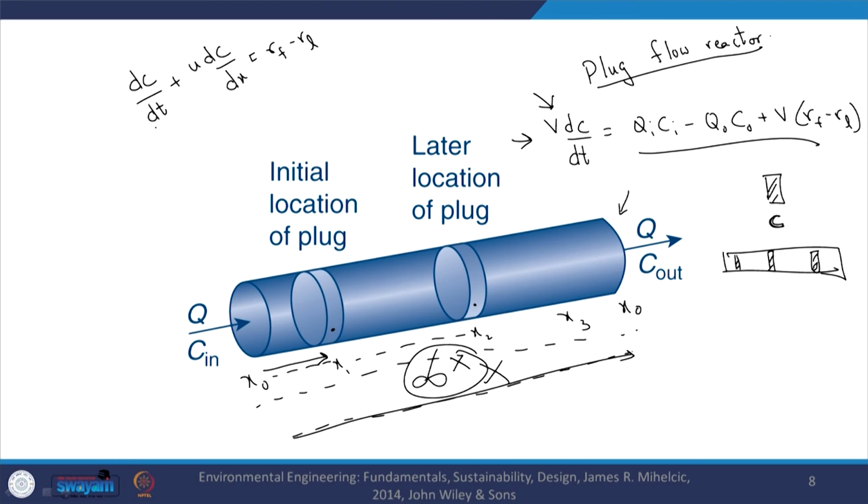But here as you see, you have concentration change with time, concentration change with distance and the rates of the different formation and loss reactions. So, if I want to apply it to this reactor or the plug flow reactor PFR, please note that these are all ideal case reactors. What can I do? I can directly apply this particular equation. So, if it is at steady state, what will it transform into? This particular term will be 0 and u dC by dx is equal to rate of formation minus rate of loss, right.